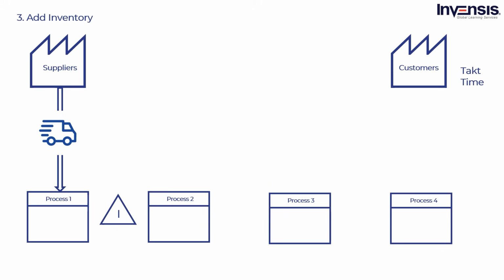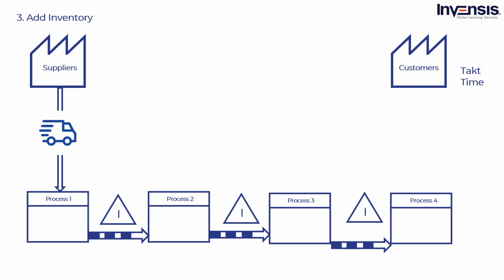Next, use the push arrows to represent material pushed from one process to the next. After all these, now in between each stage, use an inventory triangle to mark the number of parts you have in work in progress. Represent this at the end of each process. After all these steps, then mark the direction of information flows.